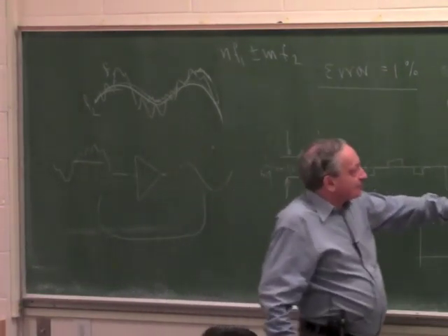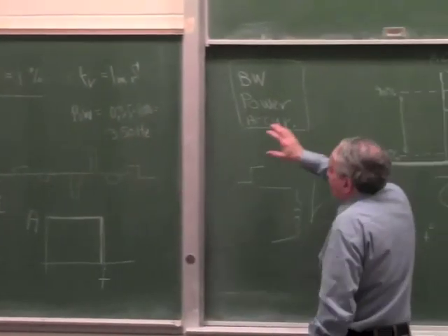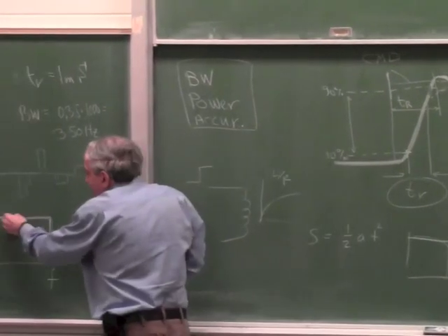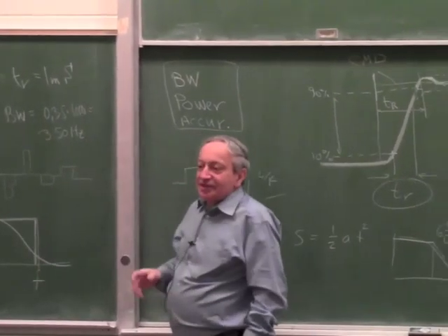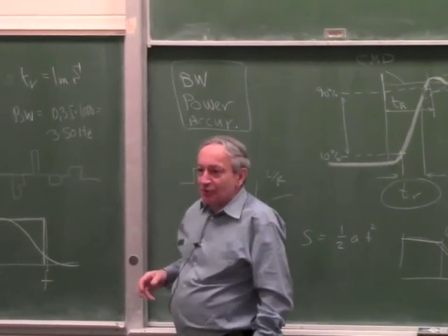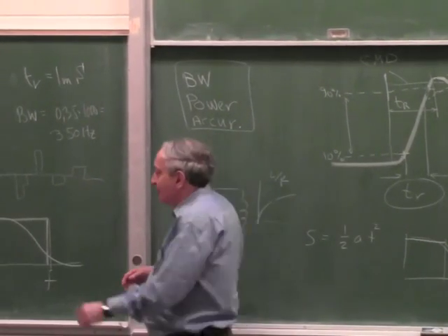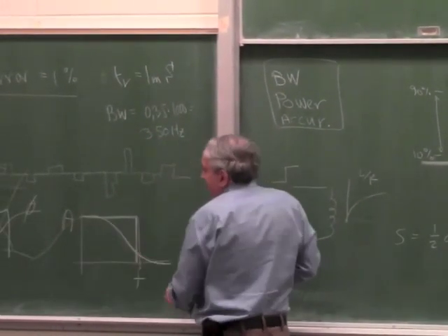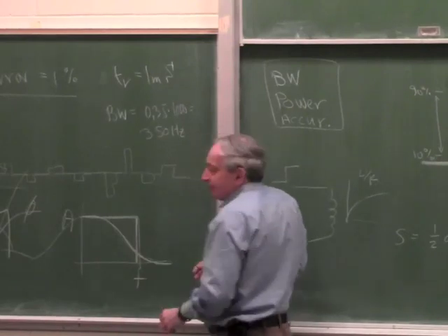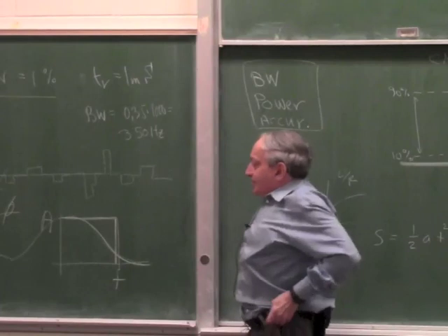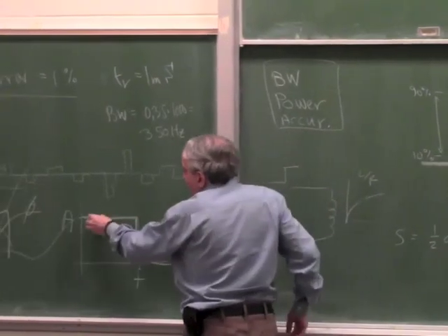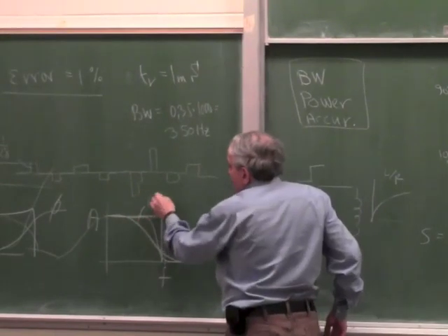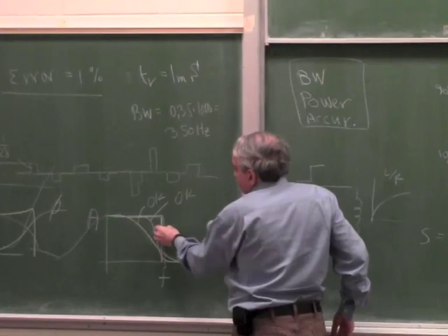So now back to this. Now we know what bandwidth the system needs. We know what filter to put, and it's never this. It's always like a nice, gentle filter. Either a simple RC or something which is called a raised cosine. It's a very popular filter in telecom. So raised cosine is like if you take the cosine waveform, it's the first part of the cosine, but it's always a gentle filter. It's never a sharp cutoff filter. Sometimes you go to a 4-pole, 2-pole or something a bit steeper like this. Okay, so this range is okay, this is okay, this is okay, and this is no.